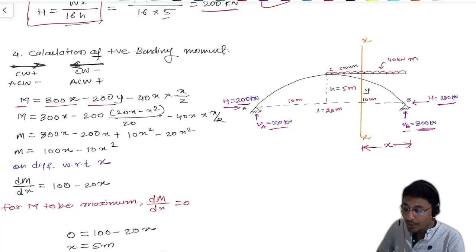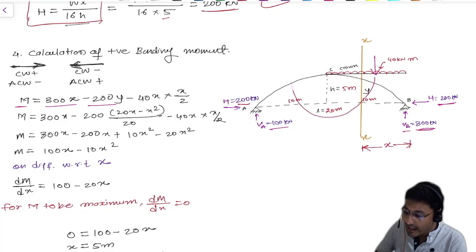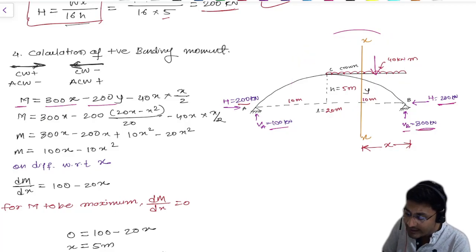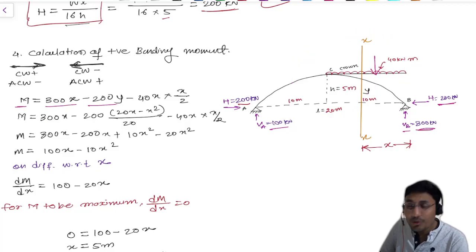Now the point load. When it is converted into a point load, it also moves in a clockwise direction, so it will also act as minus 40. But in this scenario, you are not aware of the distance in the numerical figure, so the distance is mentioned as x. So 40 into x, minus 40 into x into x by 2. Right? Why x by 2?